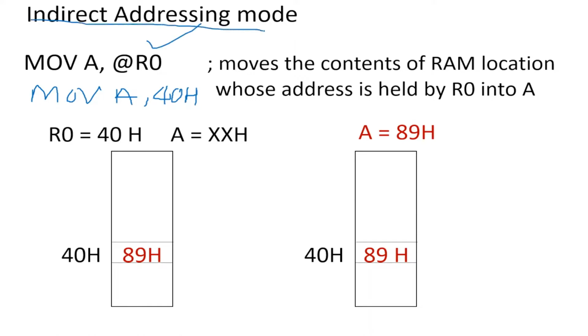Indirect addressing mode has its own advantages. When you want to deal with continuous memory locations and execute a particular program in a loop, indirect addressing mode reduces the length of the program. The program becomes very simple compared to the use of direct addressing mode. So when you want to access memory locations dynamically, or deal with a number of memory locations and access them in a loop one by one, prefer the indirect addressing mode.